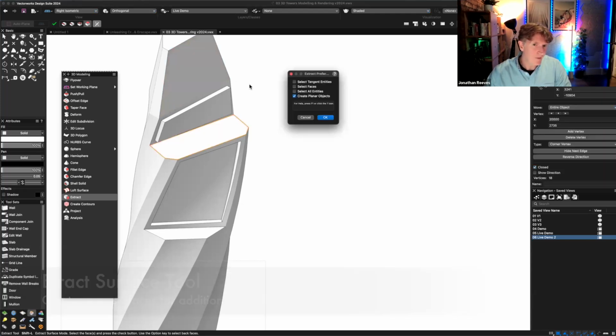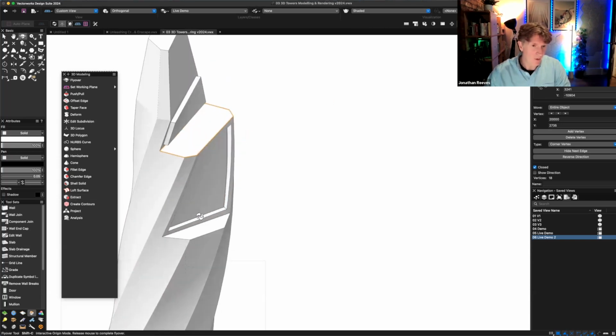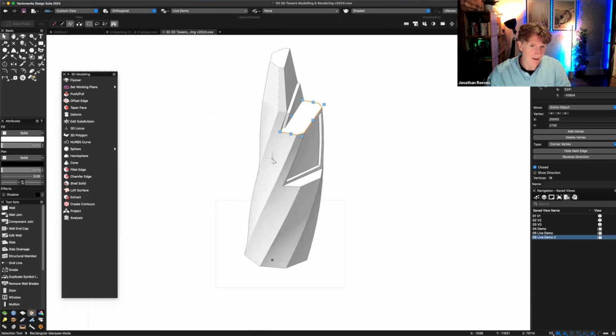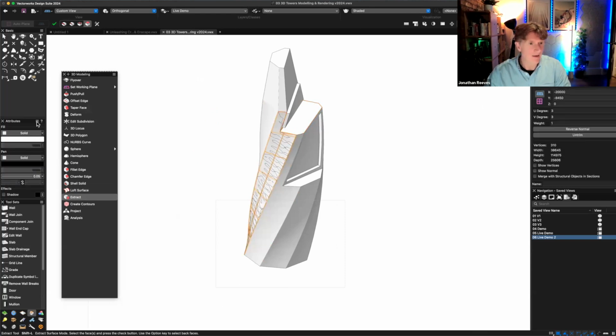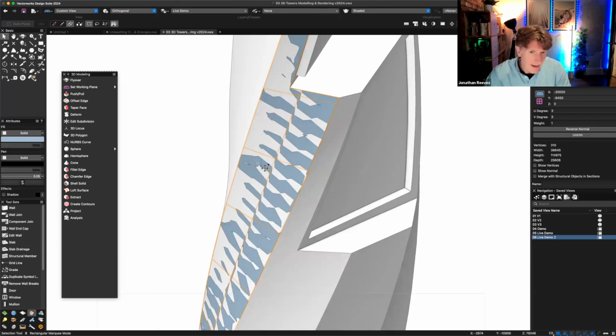Now, if the object is flat, which this one is, it's a planar object, you can see. So this is just a polygon. If I take something a bit more complicated, such as a surface here, this will be a NURBS surface. So when I click extract on that one, you can see that it gives a slightly different color, a NURBS surface here. And what you're seeing here is a phenomenon called Z-fighting, where the two surfaces inhabit the same thickness, if you like, infinitely thin.